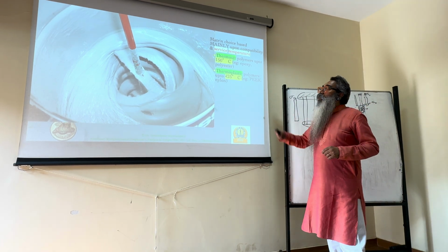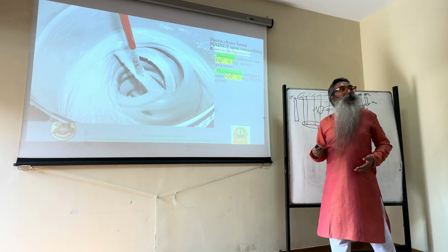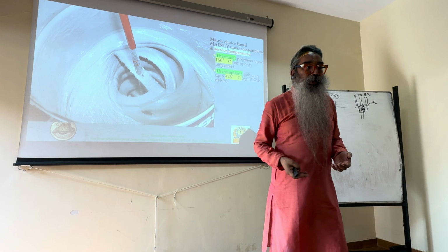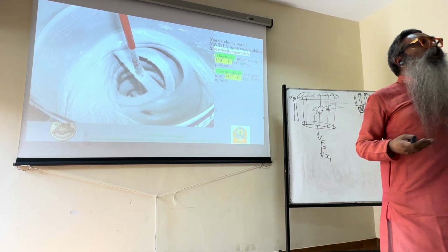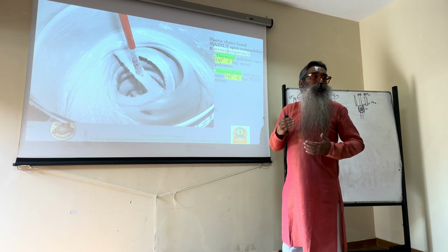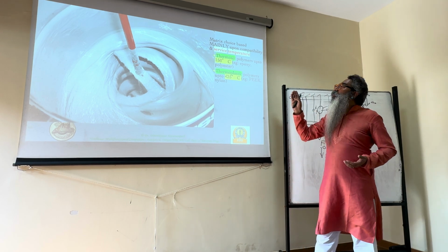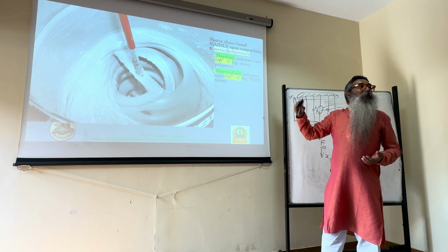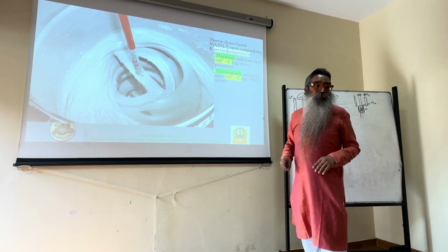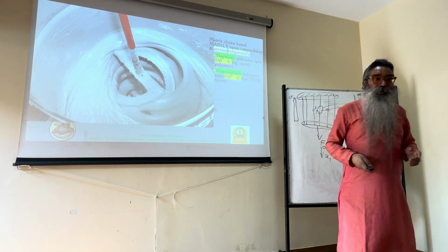Now if you go all the way up to, let's say, 425 degrees centigrade, then you can bring in, as I said, PEEK, polyether ether ketone, or nylon, which are examples of thermoplastic polymers. Again, don't take these numbers as sacrosanct. There's a wide range which is possible. There can be a few outliers for thermosets which can go beyond 150, or thermoplastics which cannot go all the way up to 425, they can go only much lesser, etc. But I'm just trying to give you the trend in terms of the overall families that are involved.